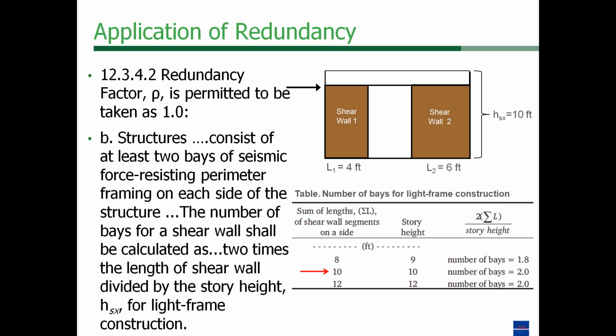So if you don't want to worry about any additional considerations, you can use 1.3 to increase your base shear and continue with your design. Otherwise, there are some fairly complex provisions in ASCE 7 that discuss the removal of an element to see if you create a torsional problem with removal of that element.